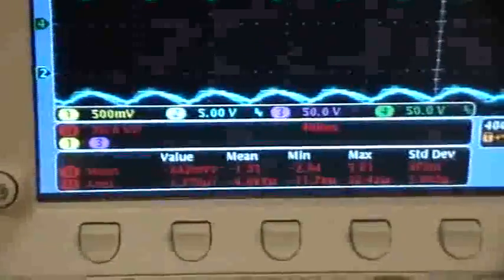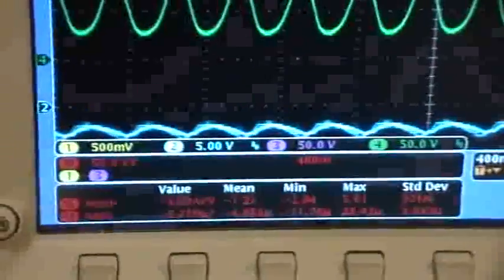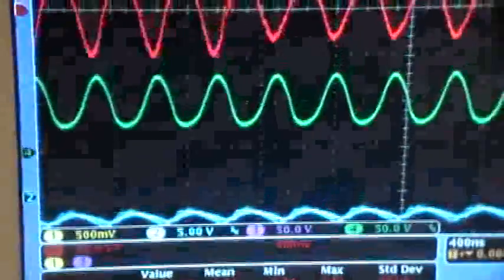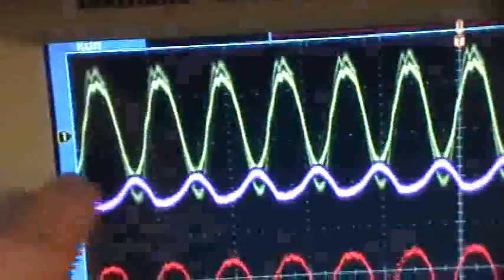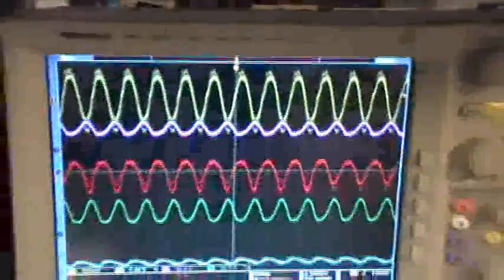Can you see all the parameters there? Negative going gate pulse, common MOSFET drains, math trace, battery voltage, CVR voltage, or current. So the math is multiplying these two traces together, and there you go.